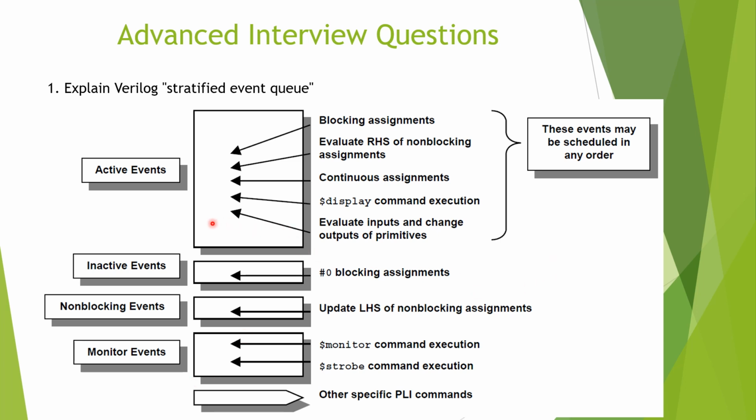The events that are included in the active events are the blocking assignments, evaluate RHS of non-blocking assignments, continuous assignments, $display command execution, and evaluate input and change output of primitives. The events inside the active events can be scheduled in any order. Then we have inactive events, which are the #0 blocking assignments. Then non-blocking events, which update the left-hand side of non-blocking assignments. And the last one is the monitor events, which are $monitor command execution and $strobe command execution.